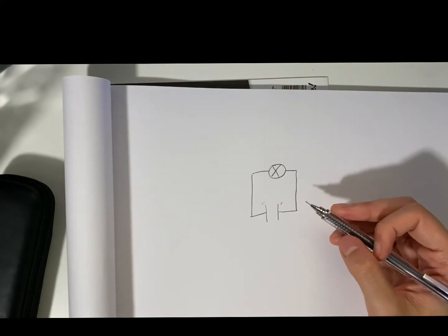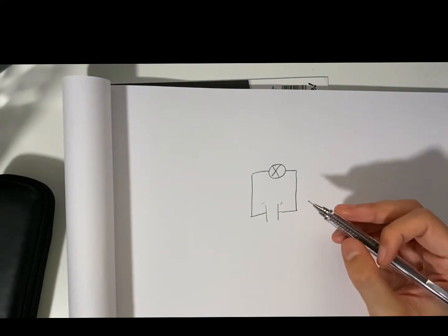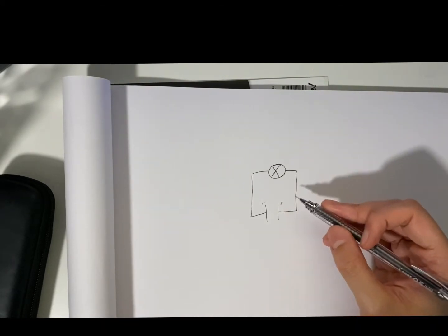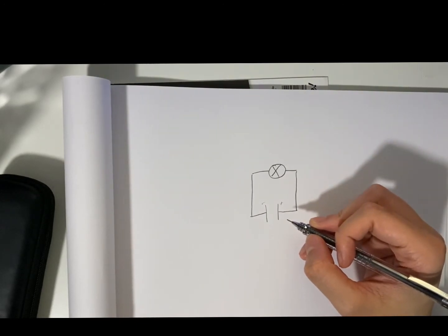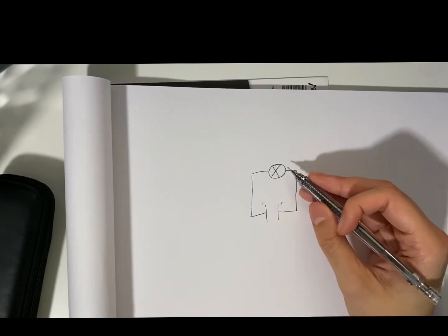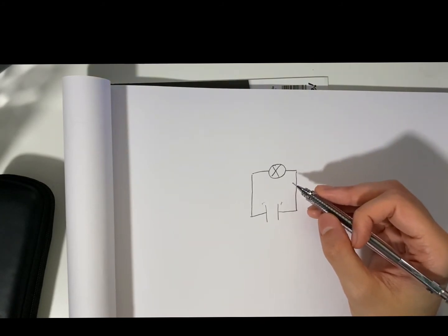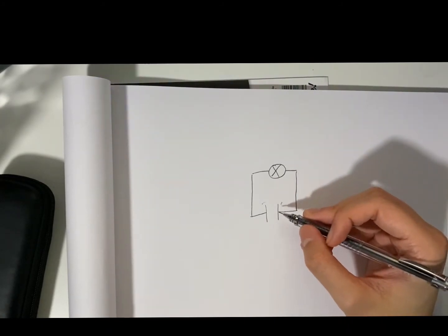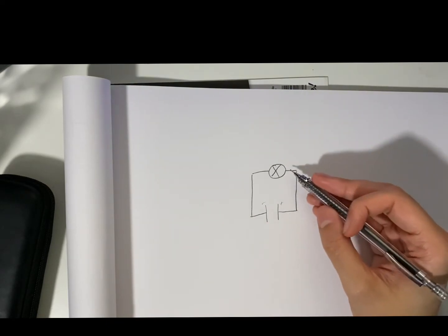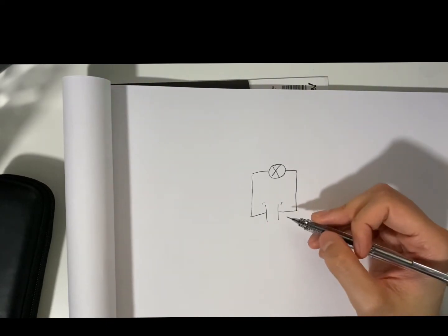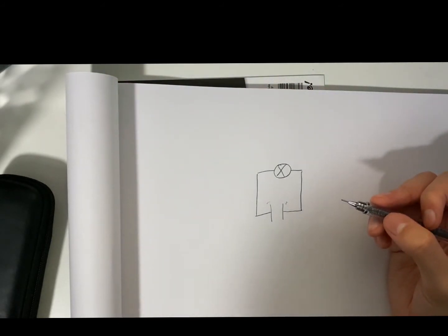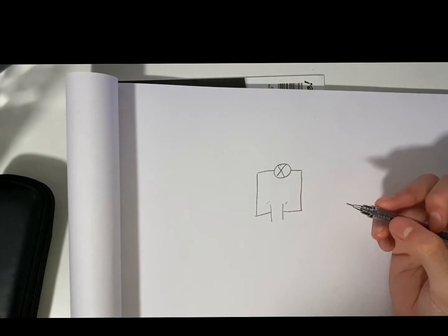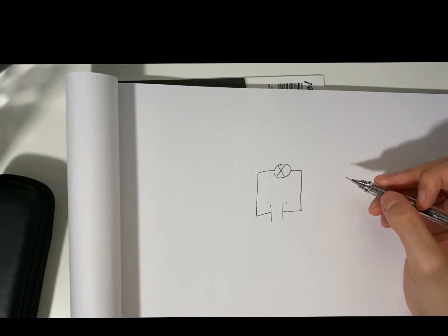Well, if we do this, it will discharge this capacitor, because it's acting as a voltage source. And again, for a brief moment, our light bulb will light up. So this is acting as a voltage source if we remove the other battery, and this bulb will light up, as they do hold voltage, charge I should say. Though, do be warned that because they can hold their charge, they can do so for many hours, and so do make sure that the capacitor is fully discharged before use.